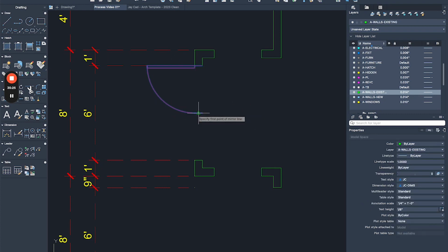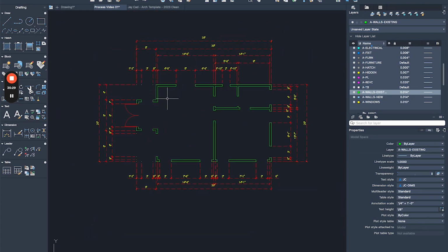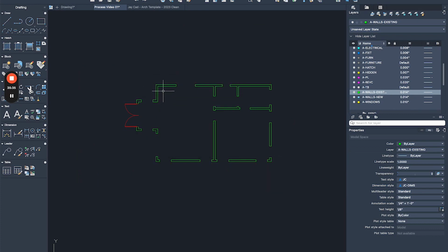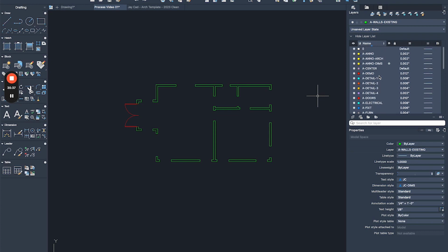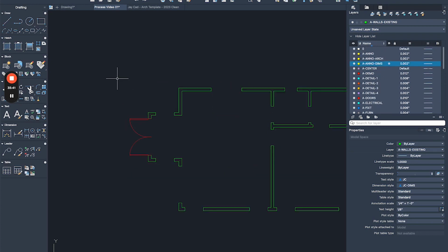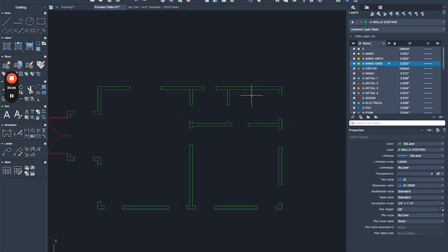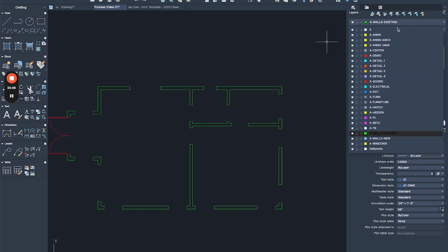All right. So now we have the door. We're gonna do a double door. This is good. Another way you can do this is we can actually freeze the layer. So layer freeze for dimensions. And boom, they're frozen. You can activate them again right here. You can click the freeze or unfreeze from layers. But now we can comfortably add the doors and the windows. Just don't forget you have them because you're gonna need them.